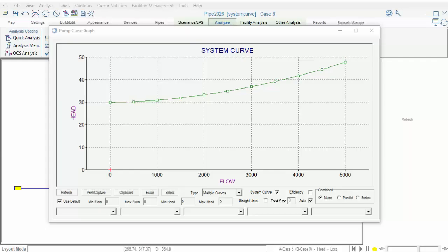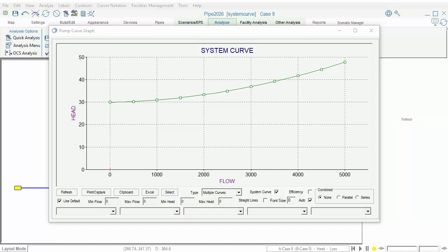A system curve is a set of head flow data which describes the performance of a piping system at a given location. This location is usually a supply pump station. A system curve is useful in determining the pump requirements and sizing for that installation. It can also help to determine the maximum flow the system can handle based on the rating of the pipes.